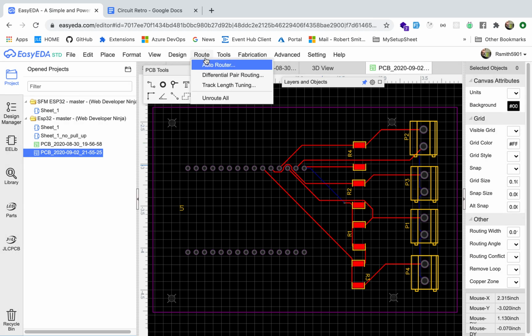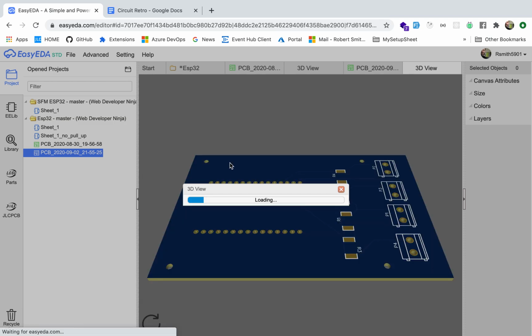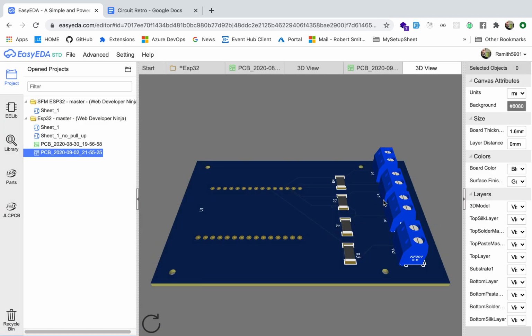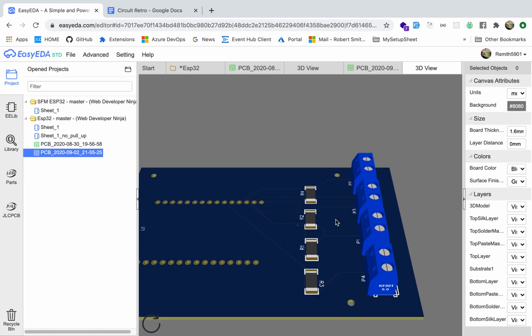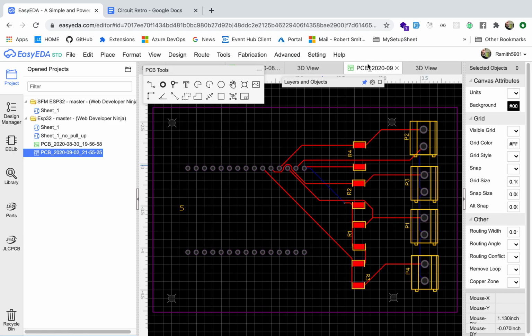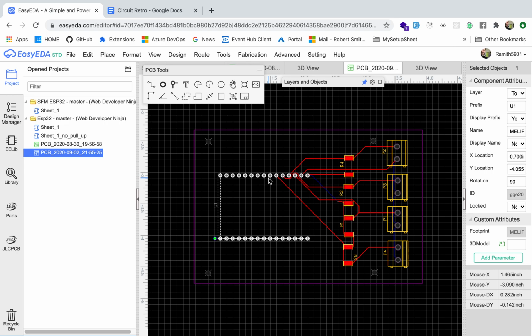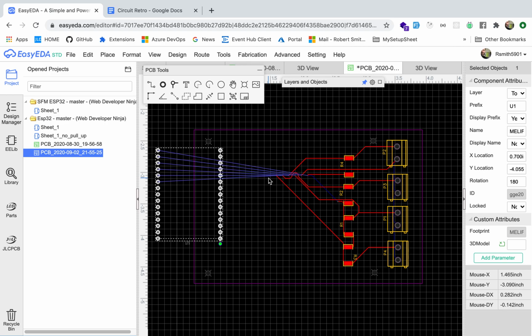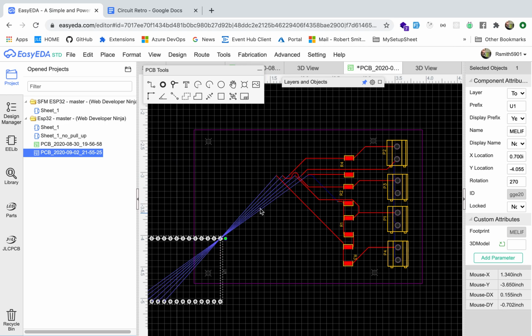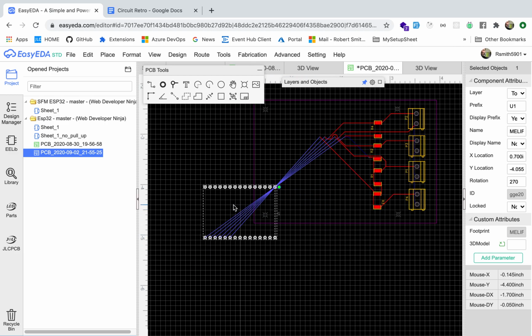I haven't flipped the microcontroller, but I did add some pull-up resistors. So here, this is kind of a nice board. We got these resistors, and now that's going to solve that floating pin situation. Just for the heck of it, I wonder, if I just, boom, it just jacked up all my traces. So I did the auto router.